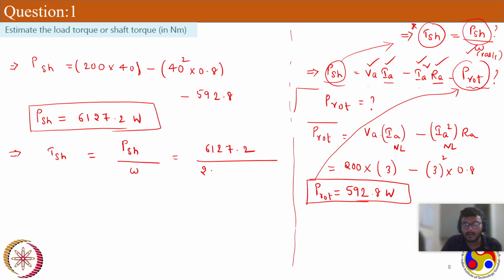What are the types of losses we experience in armature, and how we arrive at a gross mechanical power, how we arrive at a shaft power, and also we talked about the rotational losses of a motor and how laminations of a motor are done so that we can reduce the eddy current losses. We will minimize the path for the eddy current to flow so that we will achieve better efficiency.